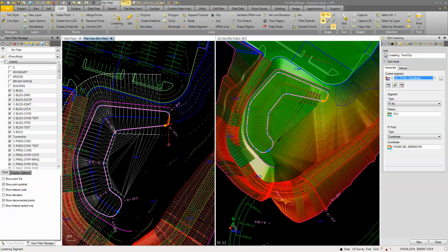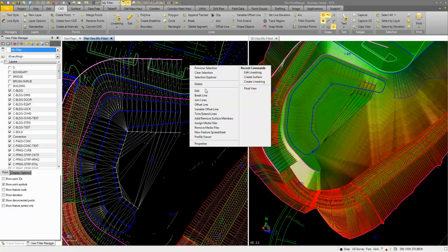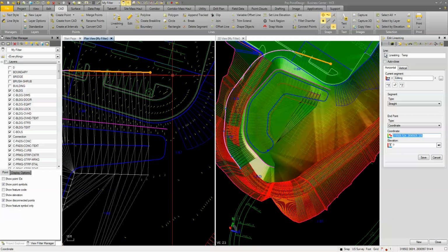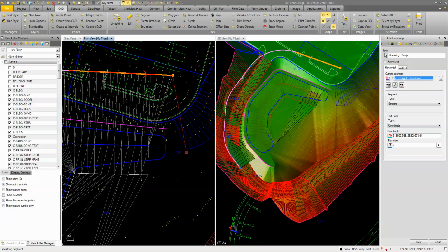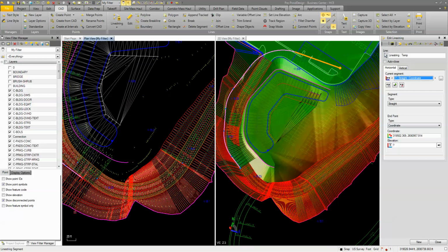So then we're gonna have to do a couple other things. Our pond or our slope didn't come out far enough on these guys. So we want to pull these guys out. So I'm gonna edit this line string, and I'm just gonna project him out over here. Okay. So let's pick a new point, make sure he's outside of that line there. So we'll hit save there. We'll come back down in here, change this point and move him out a little bit as well.